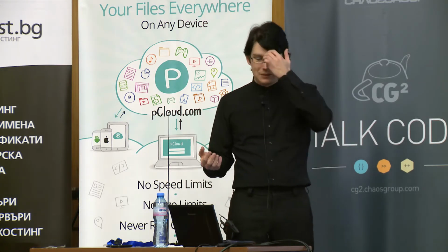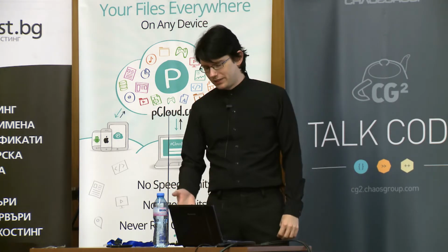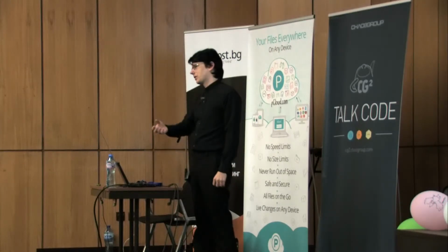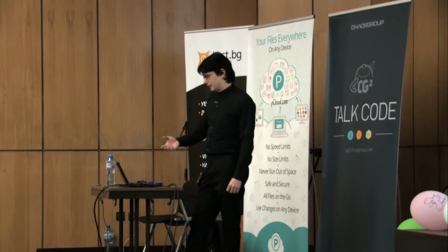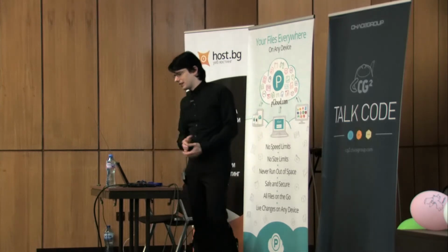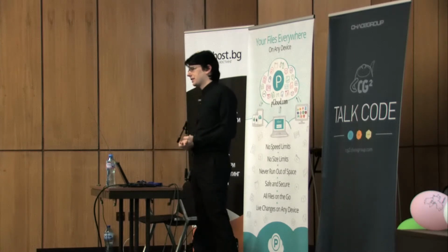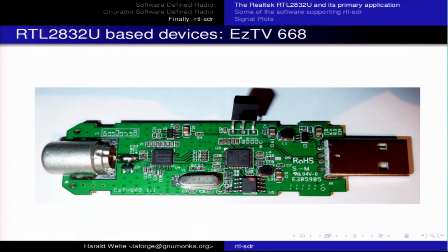Then some people figured that out, and they started to do protocol tracing on the USB to find out how on earth this chip can get set in this special mode so it sends the raw samples into the PC. After some protocol tracing, this was figured out, and a project called rtl-sdr was created, which is an open source project that talks to this Realtek chip. It activates this special mode for forwarding all the raw samples, and it consumes those samples and makes them available to various applications that may be interested in those samples.